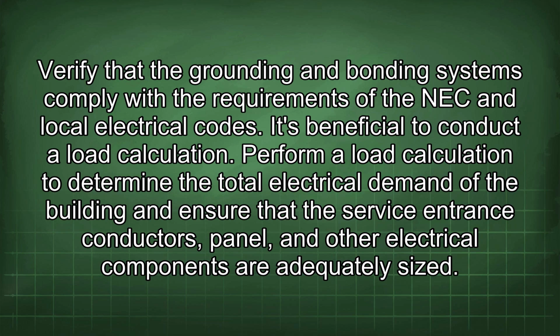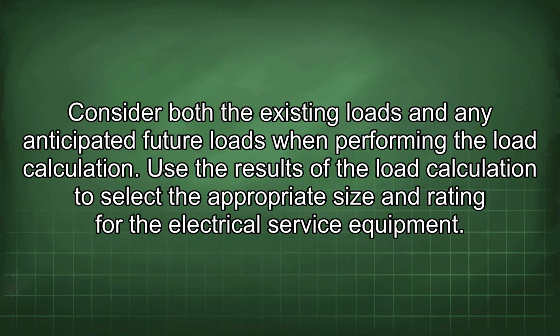Perform a load calculation to determine the total electrical demand of the building and ensure that the service entrance conductors, panel, and other electrical components are adequately sized. Consider both the existing loads and any anticipated future loads when performing the load calculation. Use the results of the load calculation to select the appropriate size and rating for the electrical service equipment.